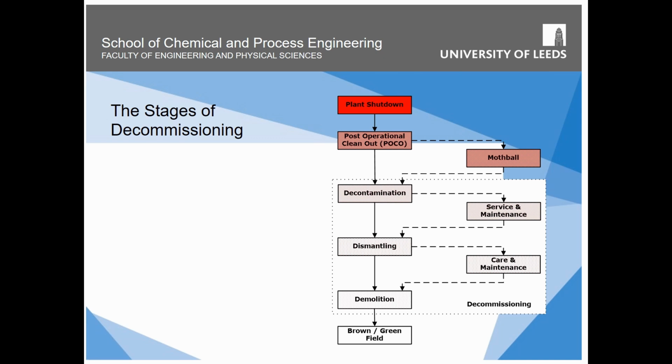We could also flush through and remove the primary coolant, the water, and that would clean that out, and essentially we'd remove all the obvious radioactive components from that. Now at that point the reactor is still working. There's nothing that we've actually taken out of service there that means we couldn't put it back in. So we could put coolant back in and we could put fuel back in, and we might decide to what's called mothball. Essentially that's a facility that's been shut down but is able to be reopened and reoperated.